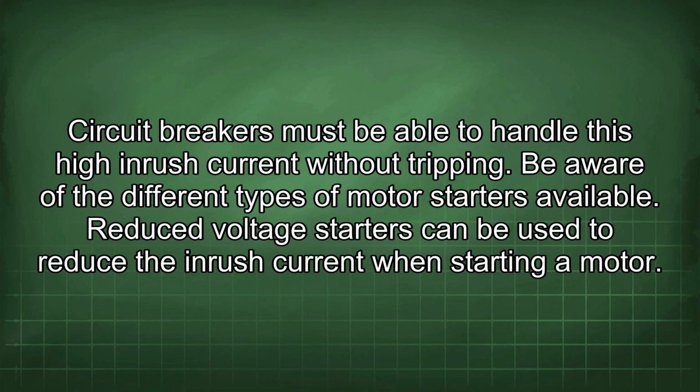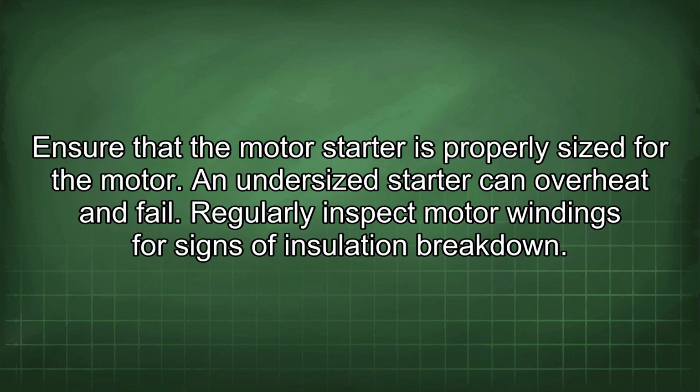Be aware of the different types of motor starters available. Reduced voltage starters can be used to reduce the inrush current when starting a motor. Ensure that the motor starter is properly sized for the motor. An undersized starter can overheat and fail.